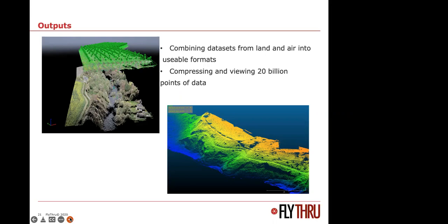And on the right-hand side is the LiDAR data that has been through post-process, and you can see that we've removed the vegetation down to, I think it was 30 centimeters on this model. And you can see clearly the footpath that exists, the larger, wider, winding path at the top, which is the one that they're going to try and replace.